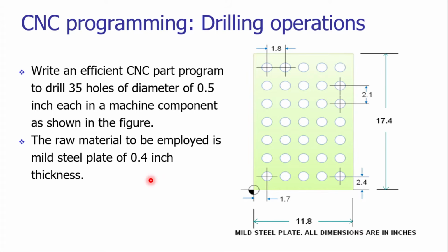So now when you get such a kind of problem, then you have to first plan your activity. In which format, in which way you will be trying to drill the holes, what would be your tool path, what kind of tool you will be utilizing. Here you have to finalize the details about the cutting tool, the feed, speed and tool path. After finalization of this information, then you can start writing the program.